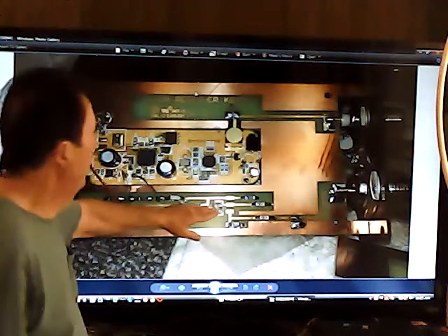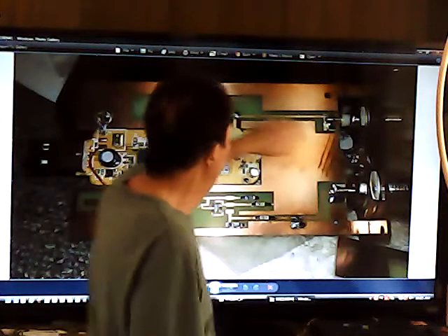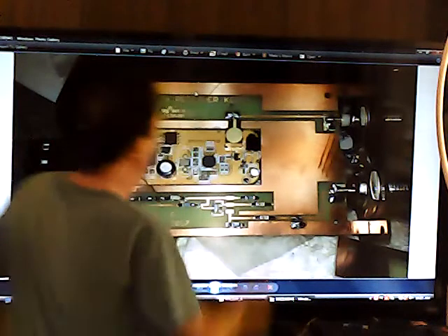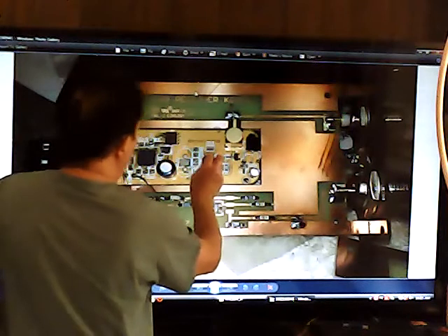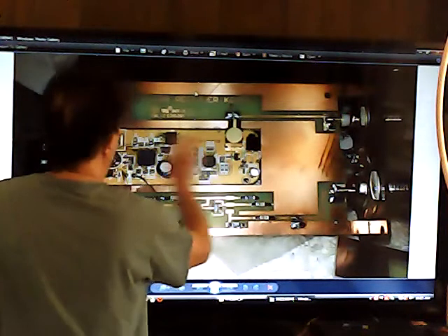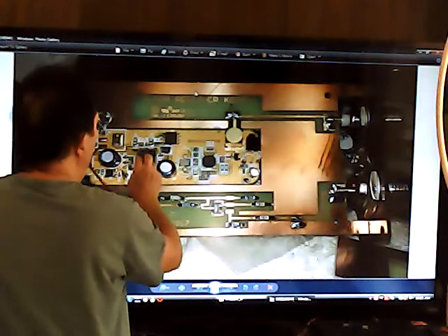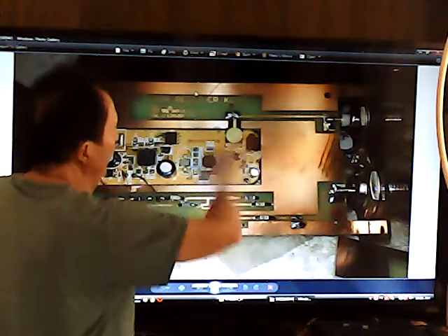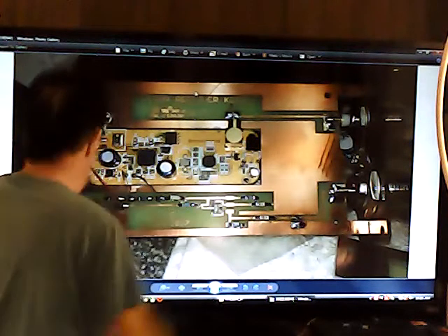If you were to use an up converter, it would come in on this antenna path and go in through the tuner on board. So you'd be talking about all of the electronics in the up converter plus the electronics in this tuner, and then going into the RTL2832 device. So you've got great layers of additional noise injection with the up converter device.